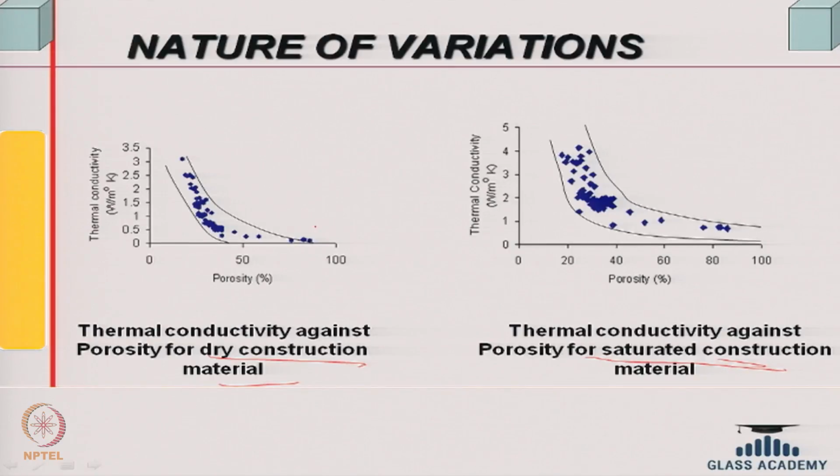So, if you want an insulation material of this kind, granular material bonded together or sintered or vitrified material, if they have low porosity, they will have higher conductivity, and with higher porosity, they will have lower conductivity. So, high porosity, low conductivity; low porosity, high conductivity. Obviously, there are other properties one has to look into. Insulation materials are usually porous, many of them are, and of course, there are varieties of other materials that could be there.